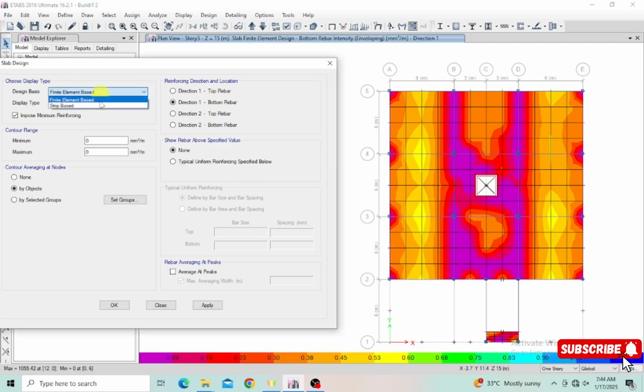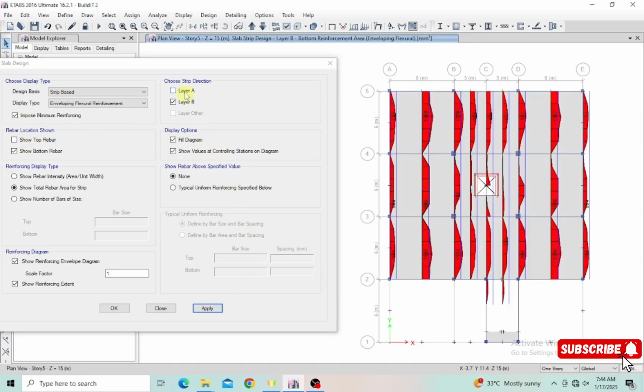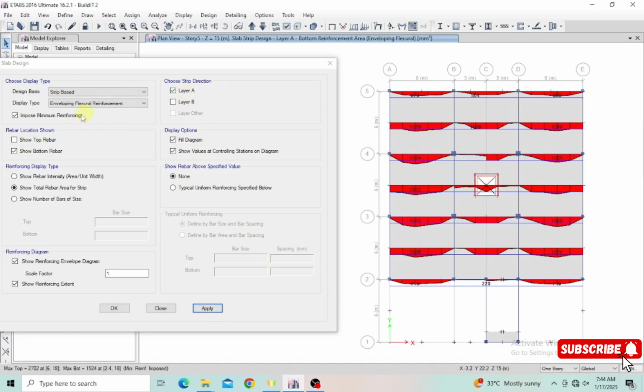So let me take you back to the strip base and just view the bottom layer, show bottom rebar at layer B. Was it A or B? Okay, A. Then apply. Let me go for the rebar intensity. Looking at this, you see that it's around 4 something for this strip. For this strip it's 4.7.